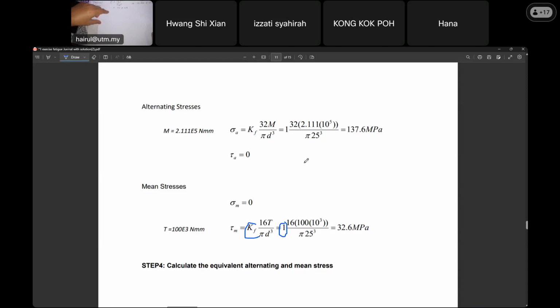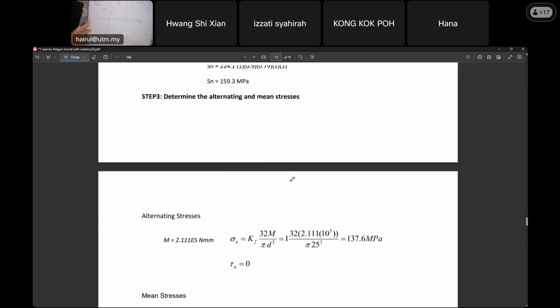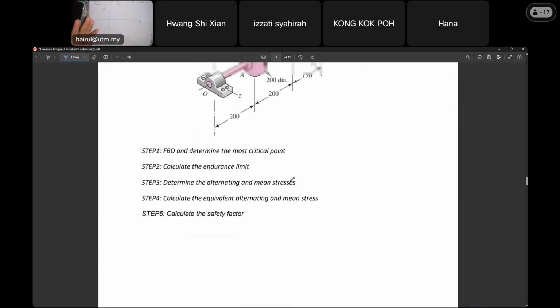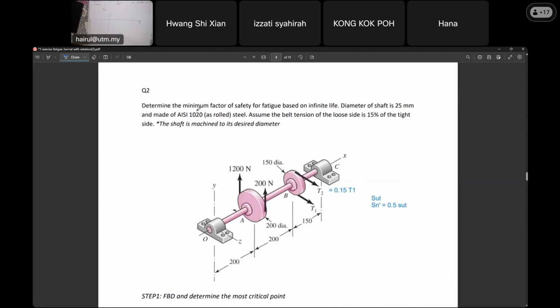Yes, yes. All right. Another thing to mention to you. Remember, as I mentioned, for fatigue analysis we do not simply calculate stress like that. Look here, class. Our bending stress plotted against time, is it a straight line or is it a curve? Is it a sine wave or just plain? Bending stress. Can you see the shaft is rotating? It doesn't say so in the question, but it's fatigue analysis. Because it is always running by a motor, the shaft is rotating.